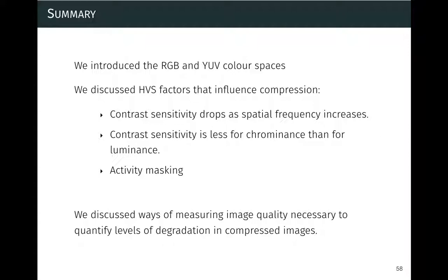So it gives us good hope that we can do something much more aggressive with chrominance than with luminance. And we looked at a thing called activity masking, which we talked about yesterday, where you put the noise matters. If you put noise on something flat, then you see it. If you put noise that would degrade your picture in a busy part of the picture, then you probably will get away with that.